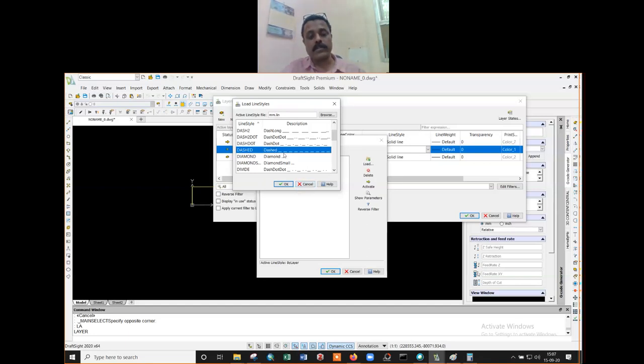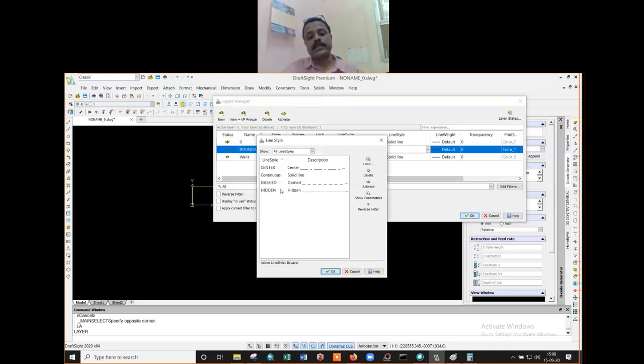So I will click on that, or I may be using this one. So I am picking this one and this one. How? I am clicking here and then pressing the control button of my keyboard and then pressing this one one more time. So whatever line type you want to include, you just press the control button and then click OK. Select, then OK. So you see, these line types are being loaded into your palette.